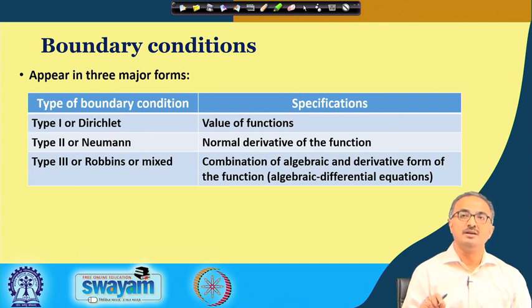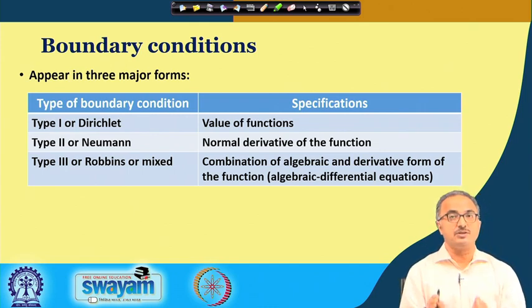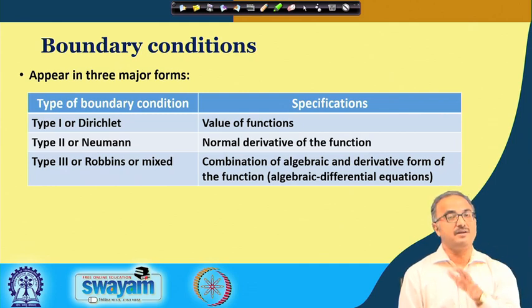It should be taken as a type 1 boundary condition. But if you are prescribing the acceleration, then it should be treated as a type 2 boundary condition, not type 1. That means the scalar field for which you are solving the particular balance equation, that value should be prescribed at the boundary to qualify as type 1, and its derivative should be considered for type 2.